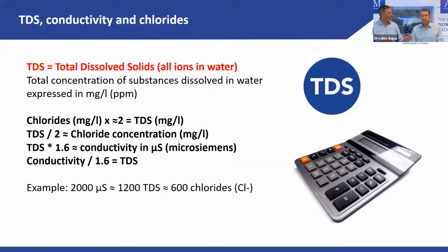So what did I want to say? I come back to tap water, for example, which has a TDS of 200. If I add in 1 cubic meter of water 1 kilogram of salt, again, this is 1,000 milligrams per liter or 1,000 grams per cubic meter, then my TDS goes up by 1,000. Part of this is sodium, part of this is chloride. Now, this TDS is the amount of these ions in the water.